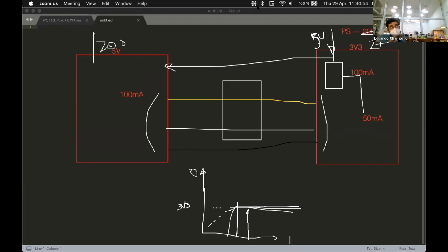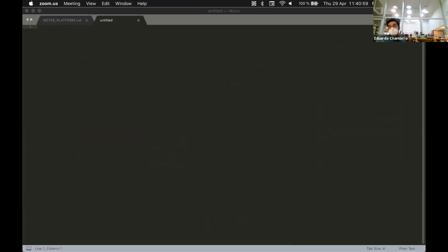Also, power supplies, the milliamps or amps is what they can max out, not what they are constantly giving. So they don't only give what you ask for them. Actually, if you need 200 milliamps and you rate for 200 milliamps, what you're doing is making the power supply work at the maximum all the time. That might lead to a shorter lifetime. Exactly.